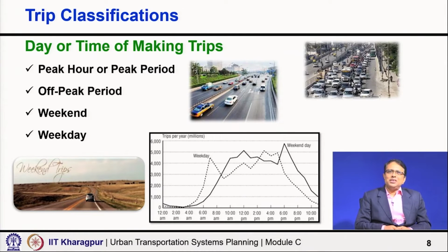So, this is again one way, because you see the congestion, most urban area congestion is due to peak hour trips. So, if you see the total number, a road capacity is fixed, every hour a road can handle so many vehicles or so much traffic. So, road capacity may be fixed per hour, and in most urban areas the total daily demand is less than the capacity of the road into 24, that value is significantly lower.